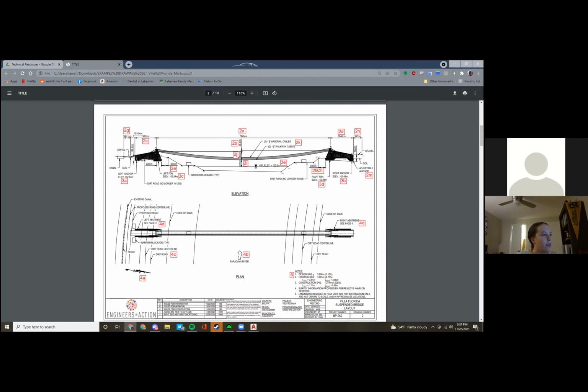And then design sag, we're just putting the sag distance, which is your percentage times your span. And then we're not showing a left and right because you should be showing that up here, or at least you're showing it from the left for this 383 centimeters value. And then you can calculate from the right by adding delta H. And so we want to see the percentage you're using here and what you're using for your calculations, but then you just need to show it up here. So this 383 centimeters should not match your F left for hoisting or construction sag. That's only for design sag. And that is all that's new on this one.